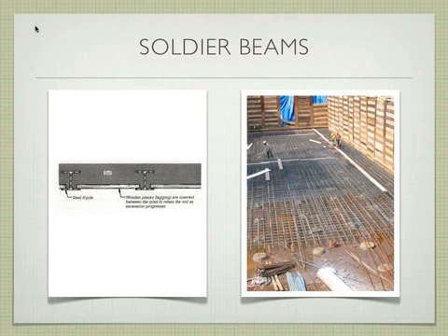Okay, so let me just draw this really fast so that it's a little bit easier to see. We're looking down in plan view. We have our wide flange, like that. We have our second wide flange that's going to be over here, if I can draw it even. The most common place that lagging, those wood planks, is going to go is on the inside. This is the hole.